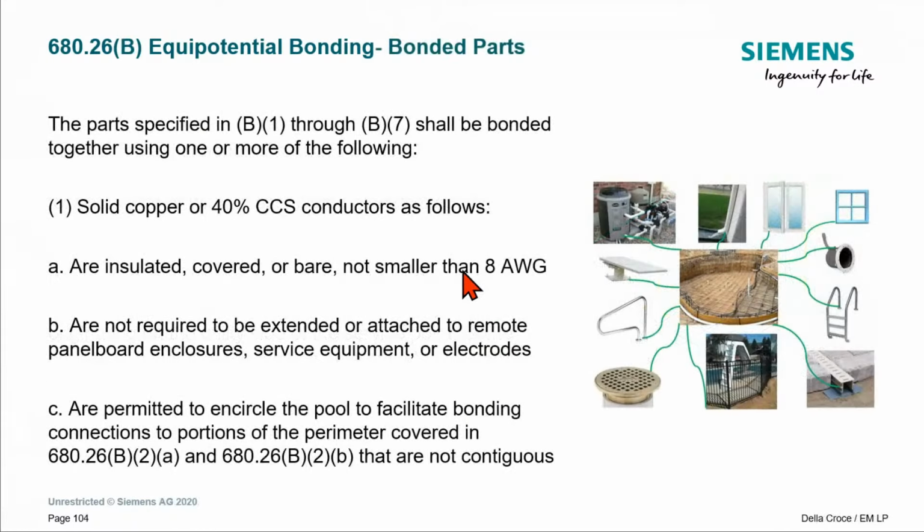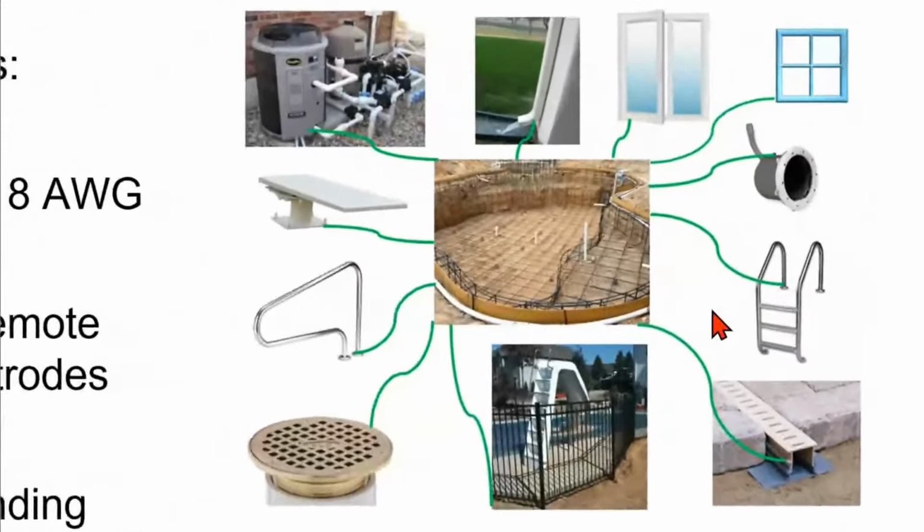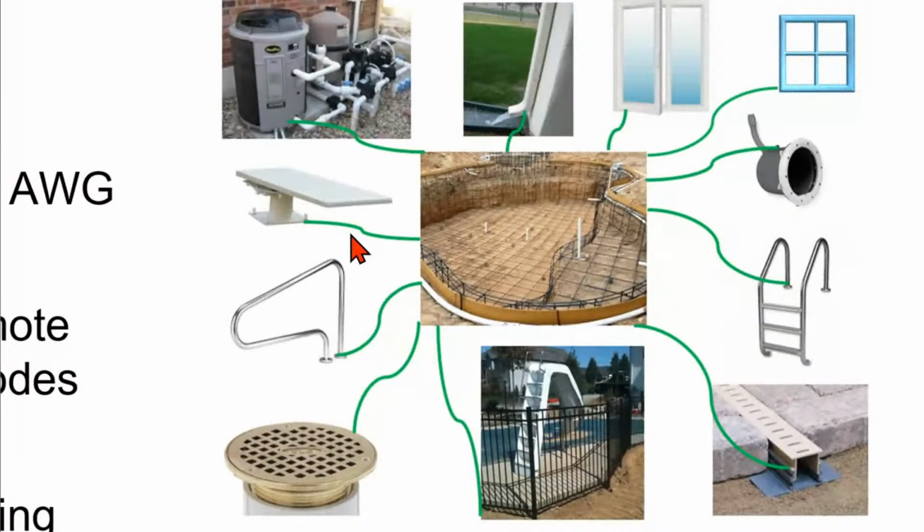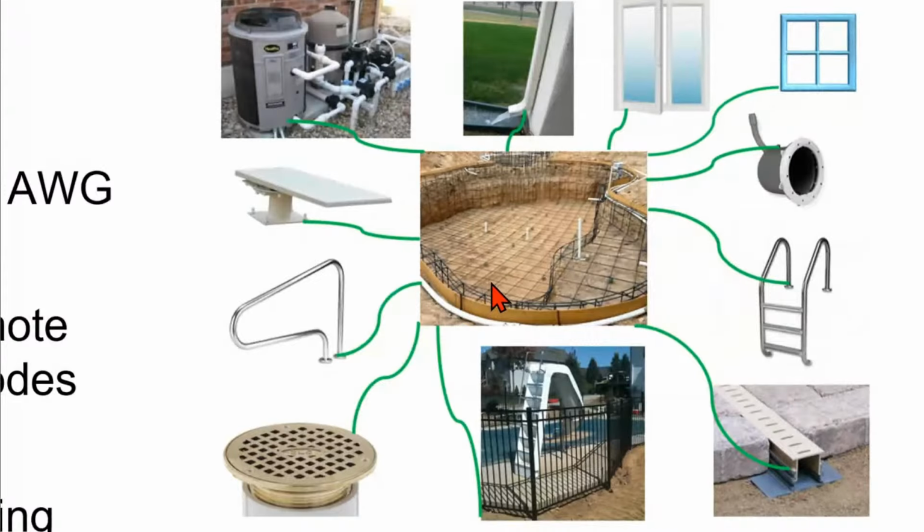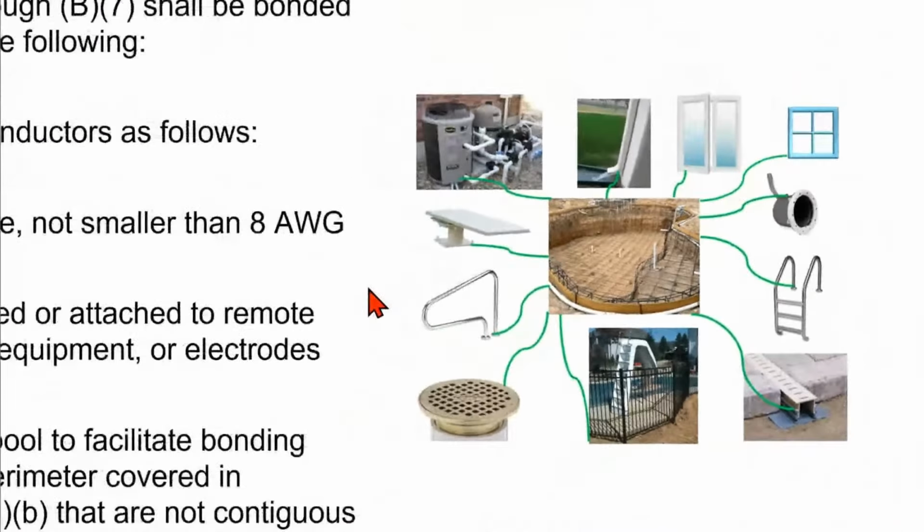We just saw, we're talking about B1 through B7. This is a great illustration we talked about earlier. This is individually, but nothing says that I couldn't daisy chain this. That's correct. It's not like a grounding electrode conductor, which can change depending on the type of electrode you're going to, the size. No, if I want to do individually to each one, I can do it. If I want to loop through them, I could do that as well. You have different options. Just get them all connected.